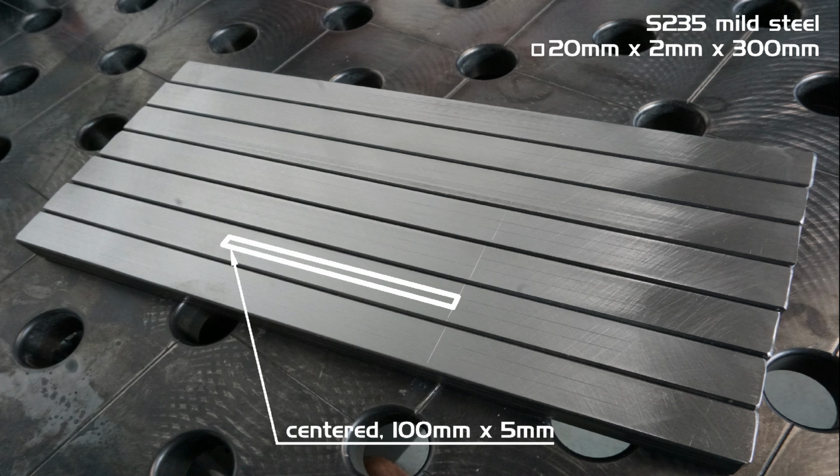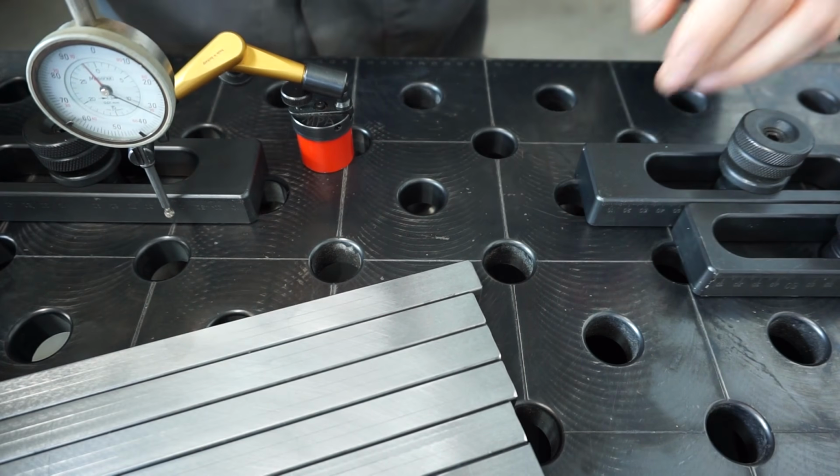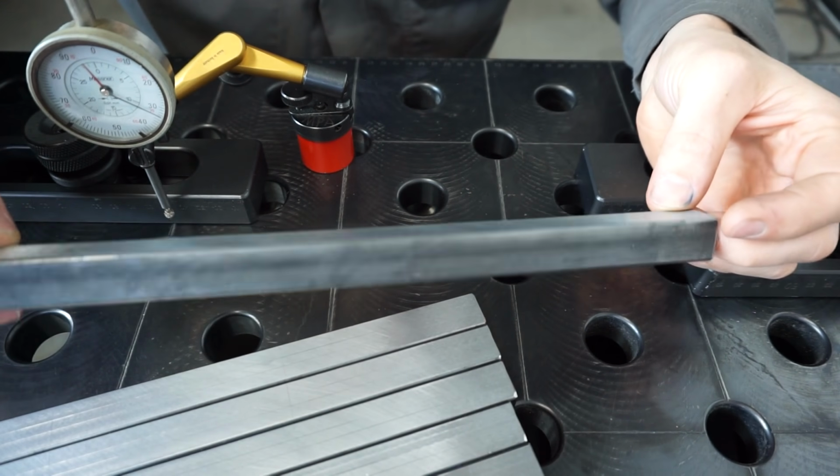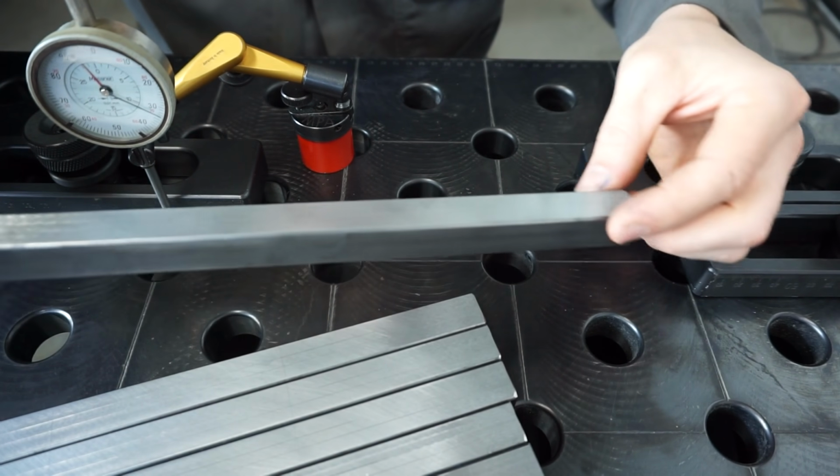And welding is done without filler metal to keep the sample cross-sections and therefore stiffnesses as comparable as possible. This of course calls for TIG welding, which I'll do with fixed current, so no foot pedal. Alright, first off let's check if our ground blanks have any bow to it.